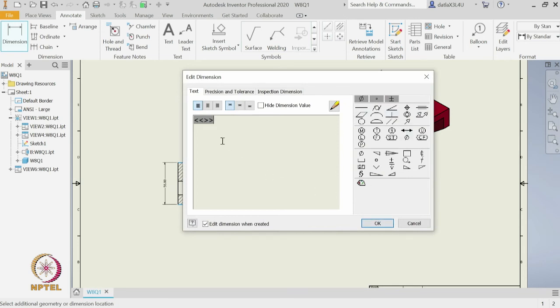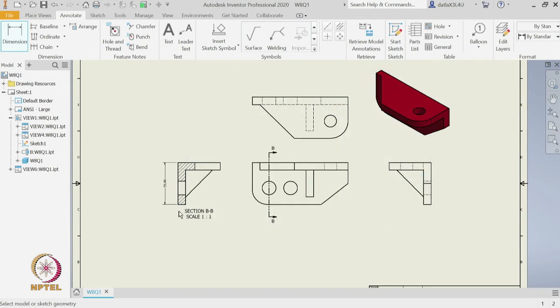So, here it brings up a dialog box where it lets you add a few more pieces of information if you want, but as of now let us say OK, because we will go with the default information of just the dimension of this line. Okay. So, let us keep doing these dimensions. We have done the linear dimension, but how about the radius? So, let us choose this circle. It has understood that this is a circle, so it is giving a diameter of 18.